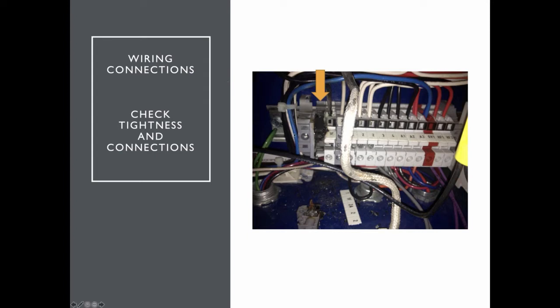It just burned us right away. So I like to do those. And if I'm having a problem on a job and it's an intermittent failure, the first thing I do is check the wiring terminal, because a loose wire can drive you crazy. You think that you have it figured out, and then all of a sudden it fails.